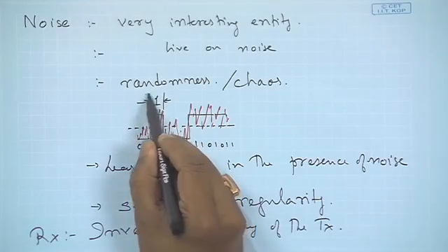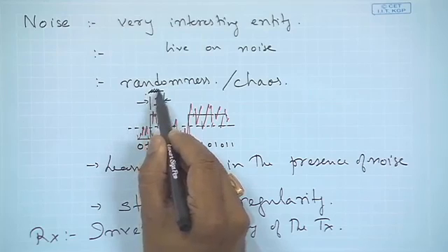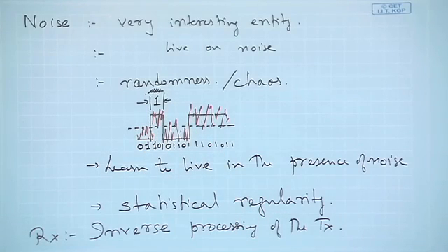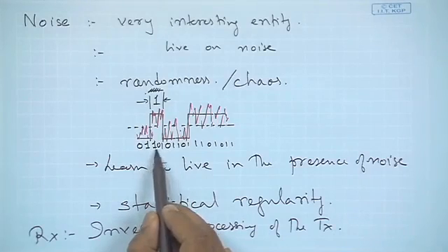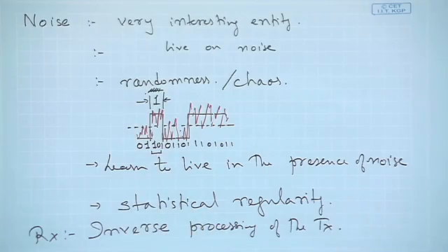So we know that 1 was sent in this period of time, right? If 1 was sent in this period of time, in that case at the receiver, even if the receiver generates a 1 0 in this period, we should actually take one of these two, or we should take a representative single bit for that duration of time. So this indicates that time synchronization plays a major role in digital communications. The kind of time synchronization we have tried to depict over here is bit synchronization or clock synchronization.